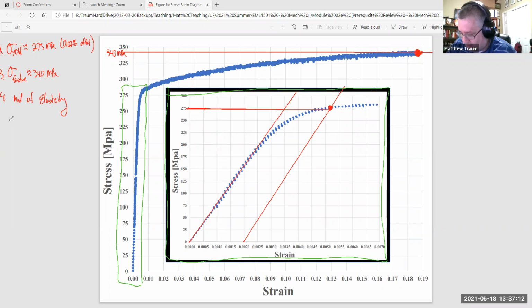And so I'm going to go to Hooke's law, which is that modulus of elasticity multiplied by strain is equal to a stress in the linear region. And now I can reorganize this like so, and calculate from the graph itself a stress and a strain in the linear region.